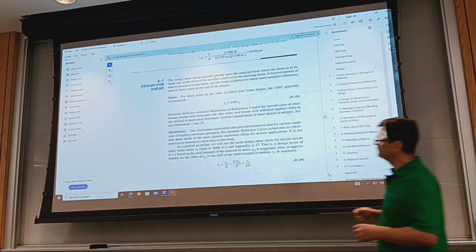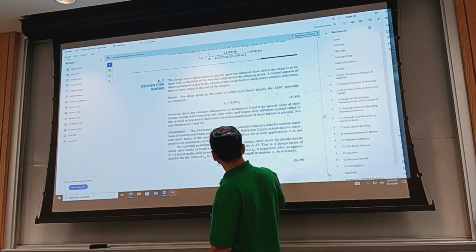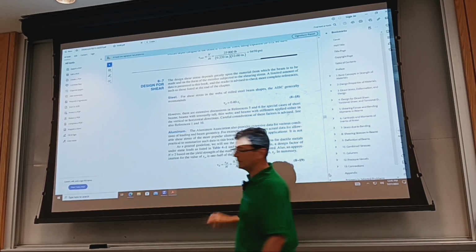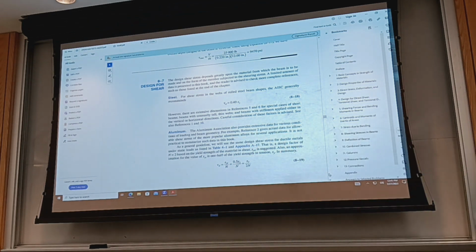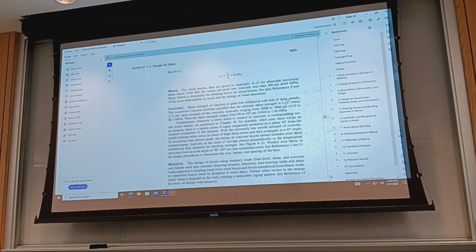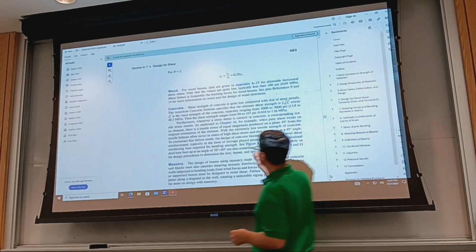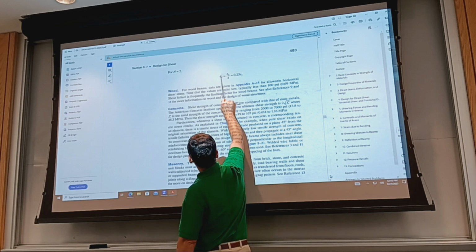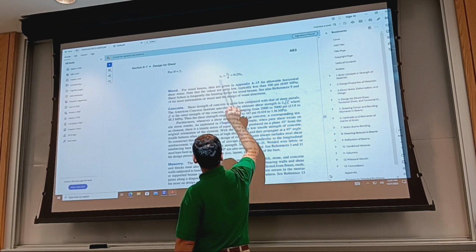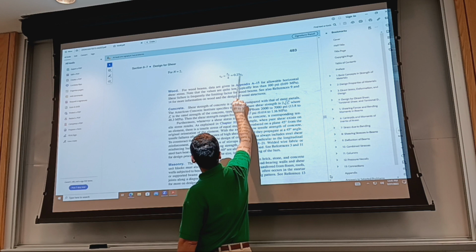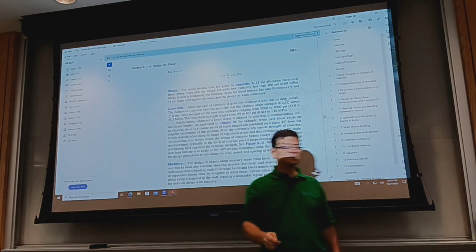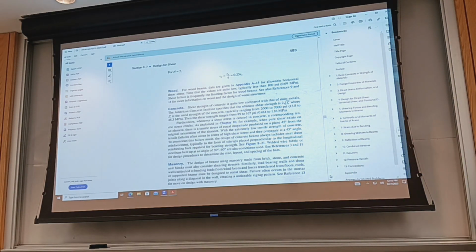For aluminum, if you take n equal 2, when working with aluminum on building-like structures, you want to limit the shear stress due to the shearing force to 0.25 times the yield strength in tension. That's the property that is already available.